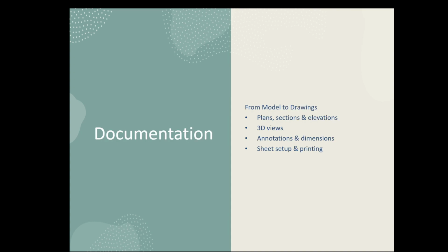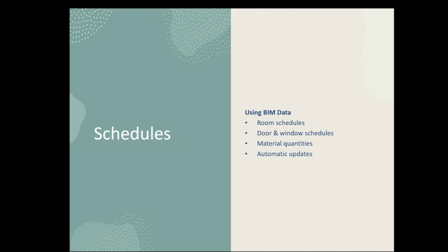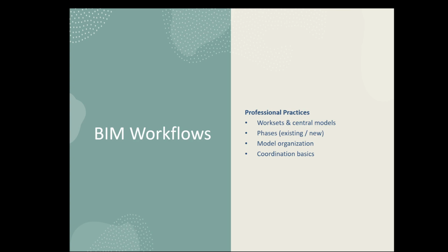And then we'll be going into the documentation part, like creating plans, sections, 3Ds, annotations, all those things from the model into the drawings, and along with that we'll be creating schedules, room schedules, how doors and windows schedules are created, material takeoff, and how they update automatically. All those things I'll be giving a brief idea.